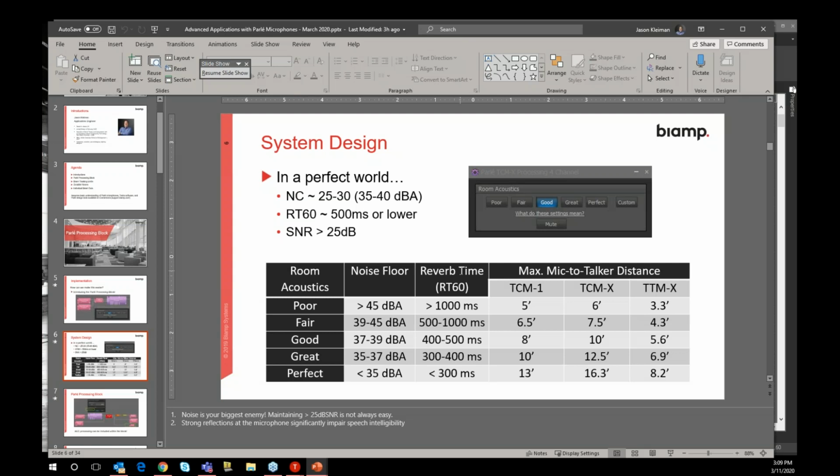Because while we're saying that mic to talker distance, of course, is going to be less than that 18 foot because we're standing or sitting, so there's a difference in height there to your actual mouth and the microphone, and the ceiling would still be a little higher. But with any ceiling microphone, you've really got to keep an eye on your signal to noise ratio and the distance.